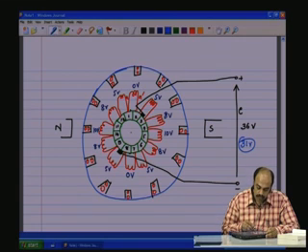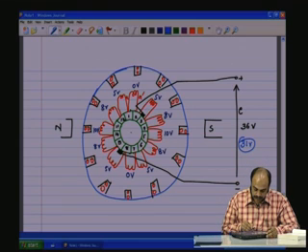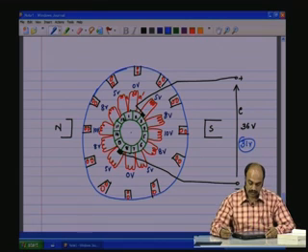In the earlier position, when it was kept at the orthogonal position in the neutral zone, any coil at that position would have 0 volts, and therefore the brush will not short the coil, and even if it shorts there is no circulating current. Here, because the brush is not in the neutral zone, at the point where the commutator segments change over, the coils are shorted. So, the induced voltage across the coil is around 5 volts, which means the 5 volts get shorted through the two commutator segments because of the brush. So, there can be huge circulating currents in the coil winding, which could result in a lot of I square R losses.